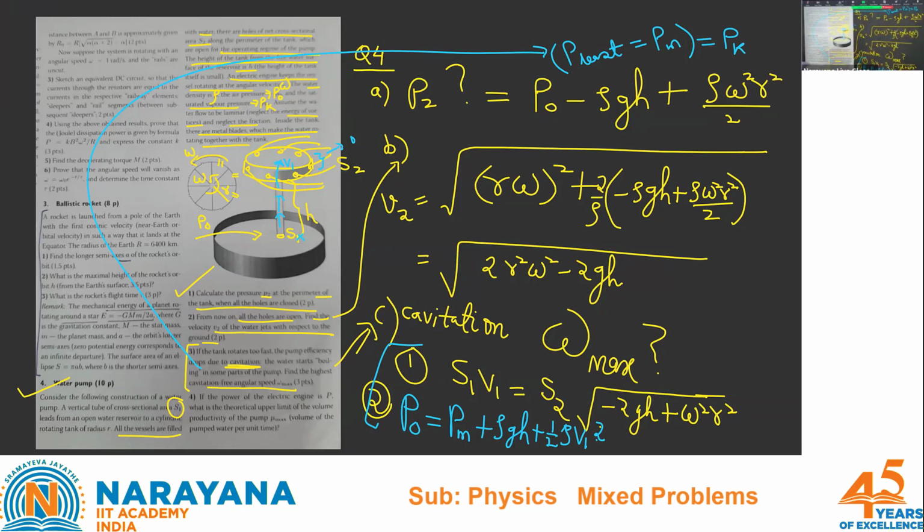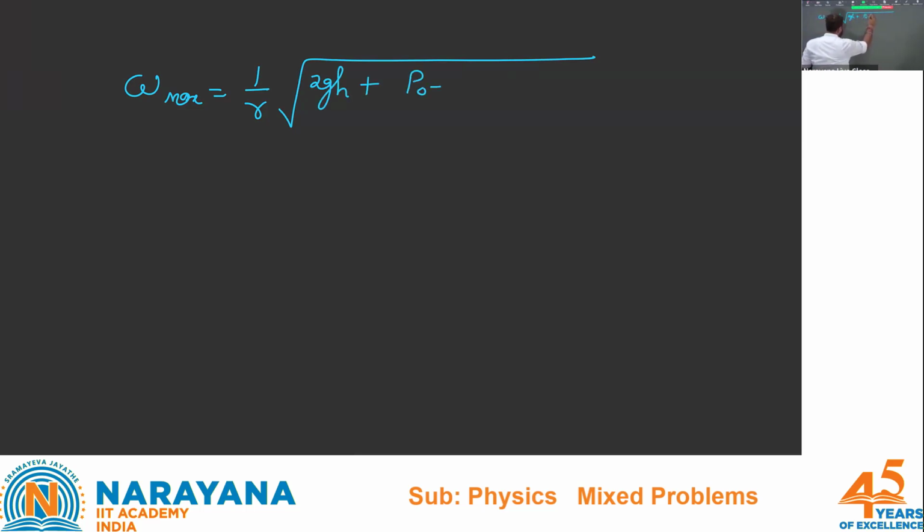I'll tell you, when I substitute PM to Pk and solve these two equations, one result that I will have is omega max, and that comes out as 1 by R, after solving all the equations, root of 2gh plus P naught minus Pk upon rho minus gh whole multiplied by S1 by S2 the whole square.